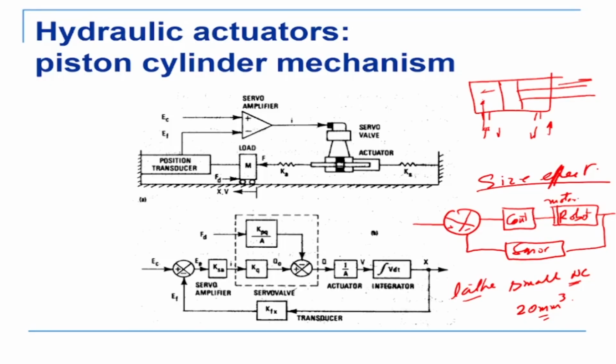Why? Because this motor which is there, if you make a very small motor, the small motor will not be able to generate that kind of power that is required to cut material. Now when you are cutting material on a big lathe or a small lathe, the cutting forces do not change because material properties do not scale. So if you're cutting 1 millimeter of steel in a big piece of steel or 1 millimeter of steel in a very small piece of steel, the cutting forces will be exactly the same. Why? Because cutting forces do not scale. Okay, so we cannot shrink a robot or an NC machine and make a very small robot.